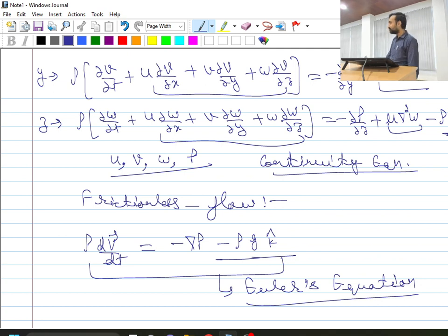So this equation is applicable for any type of flow, in frictionless flow. Every type of frictionless flow, right? Yes. But Bernoulli is only for a streamline. In every type of flow there will be streamlines, but application of Bernoulli will be only along a single streamline.